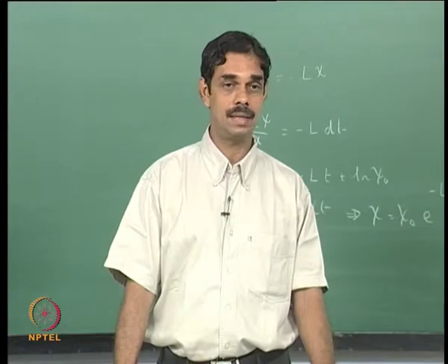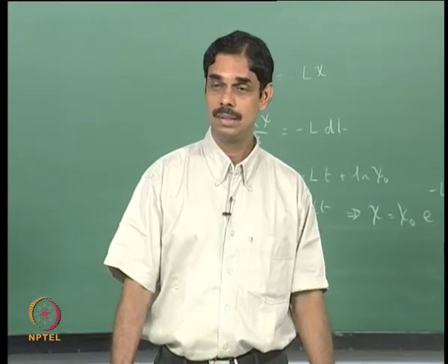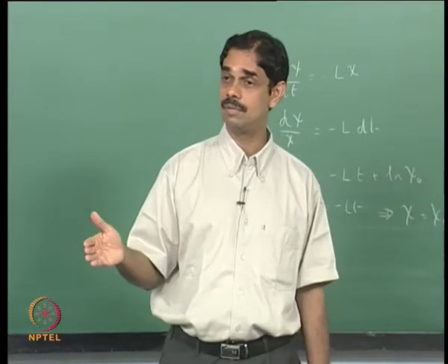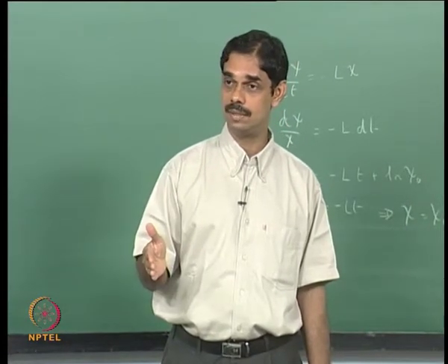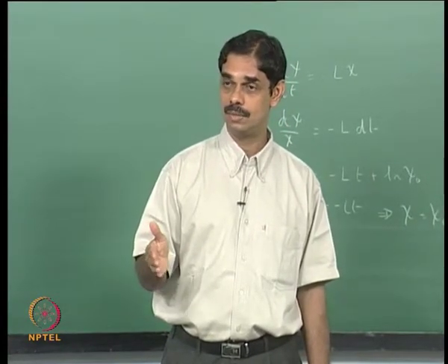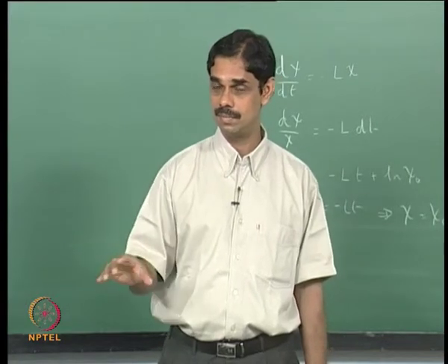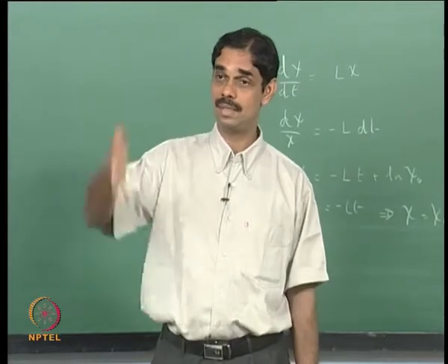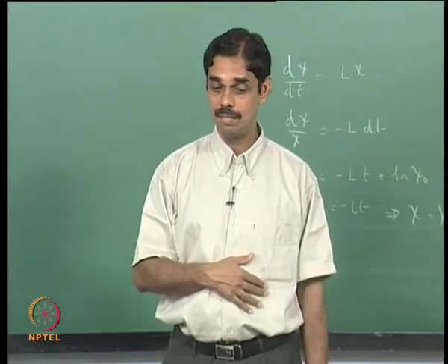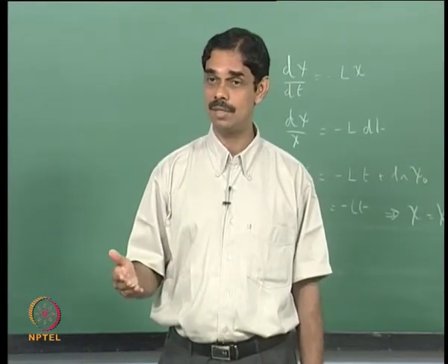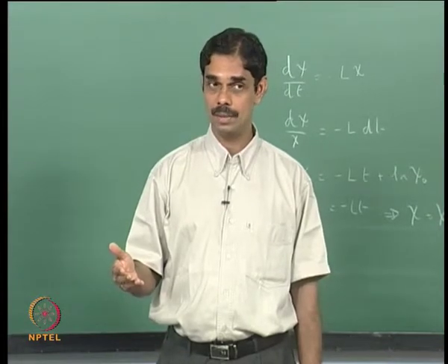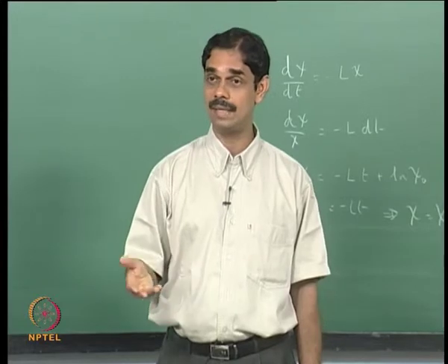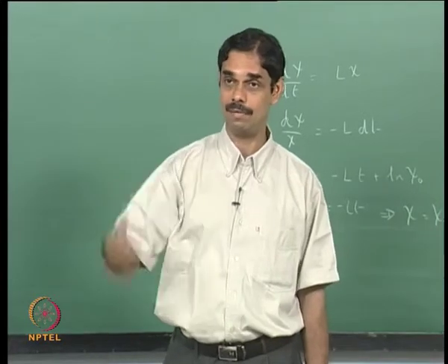If you were looking at a resonance phenomenon, your amplification goes like the inverse of the distance between the forcing frequency and the resonance frequency, right? There is a 1 over distance kind of relationship, and as you approach the resonance you get infinite amplification. But here instead of getting infinite amplification, we are looking at large amplification. So epsilon is 0 and then this becomes the eigenvalue and this inverse gives the amplification.